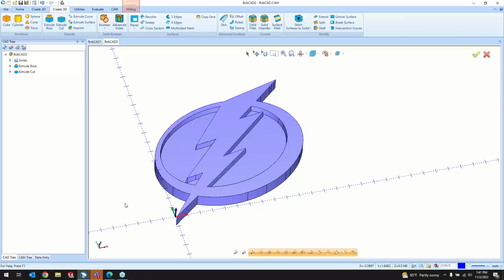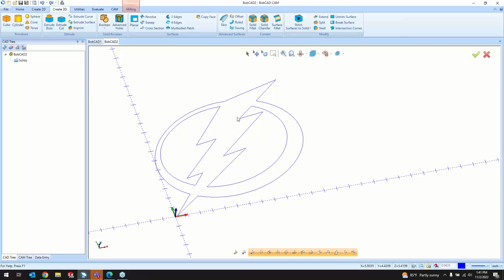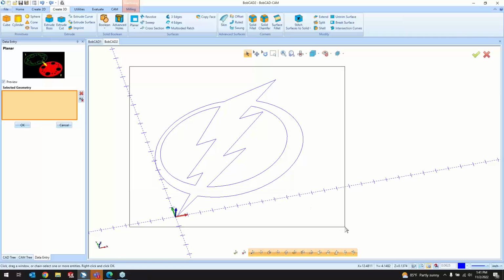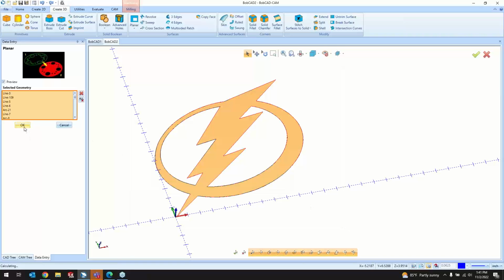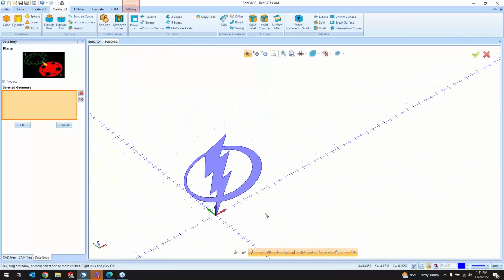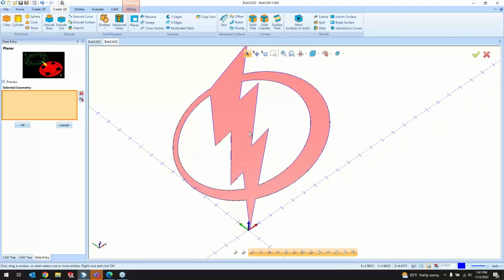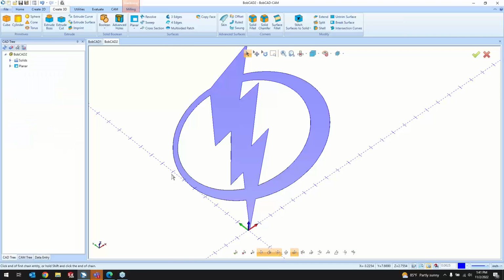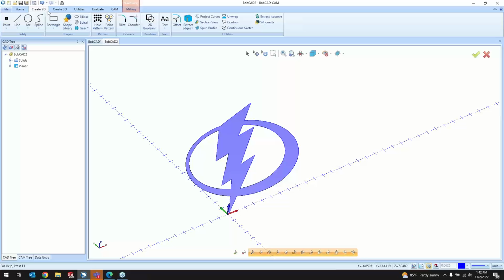Yeah, so then from there, that's our 3D modeling from an image that was vectorized, and then 3D modeled here. Thinking of some other options that we have. If we want to just create a surface for this, we can go to planar surface, highlight the whole drawing there, and create a flat shape from our 2D wireframe. That's about it, because it's a flat shape. We don't really have skin surfacing options. That's for curved 3D wireframe, revolve surface. Yeah, I think that's about it with create 3D.